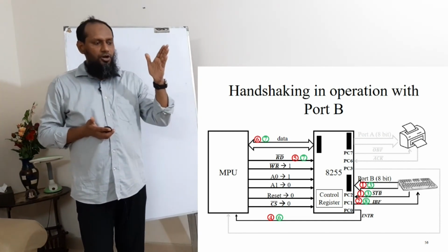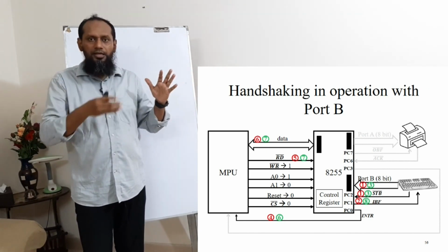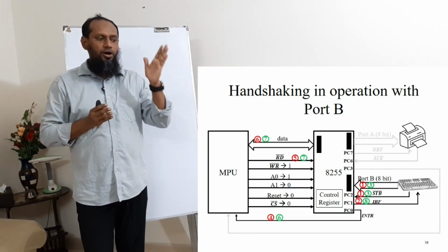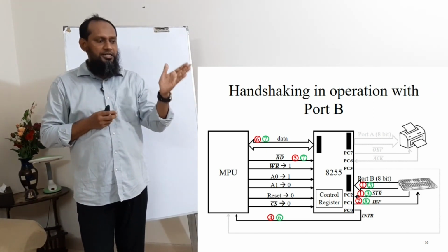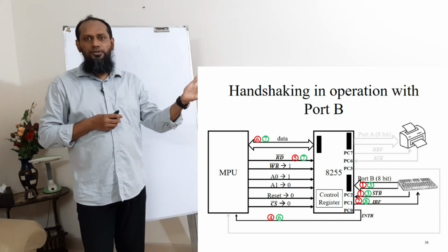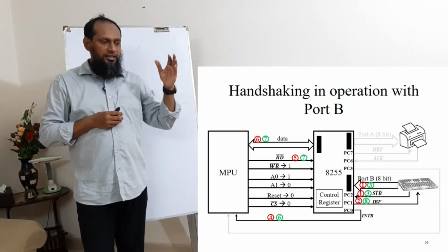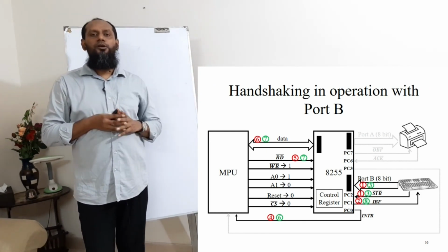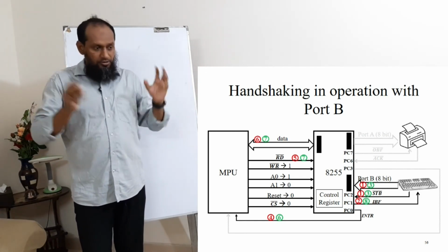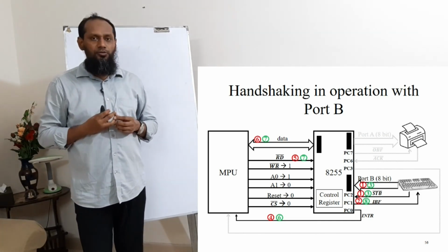On point 6, the interrupt is done, complete, like it was calling, so it got the response, I am done. On timing 7, data will come from 8255 to the microprocessor unit. When the whole data has come to the microprocessing unit, the interrupt will get deactivated. That means the IBF for the keyboard will deactivate.